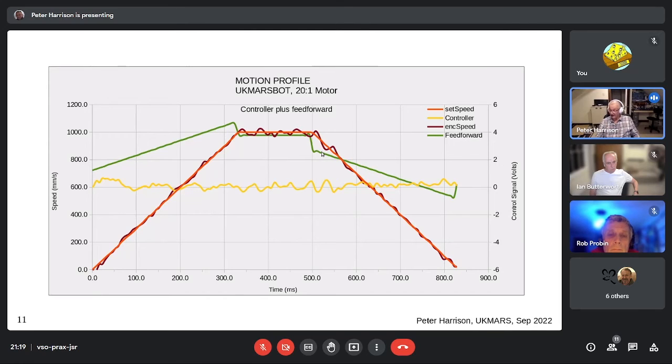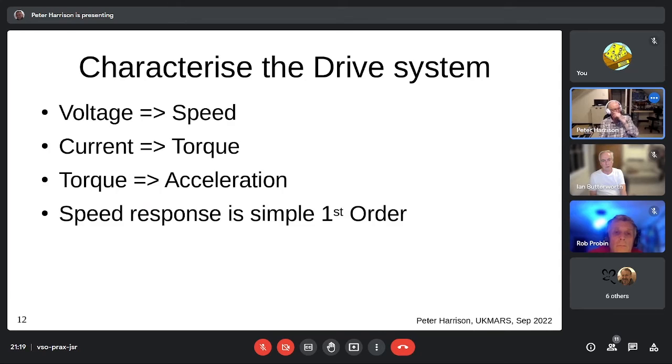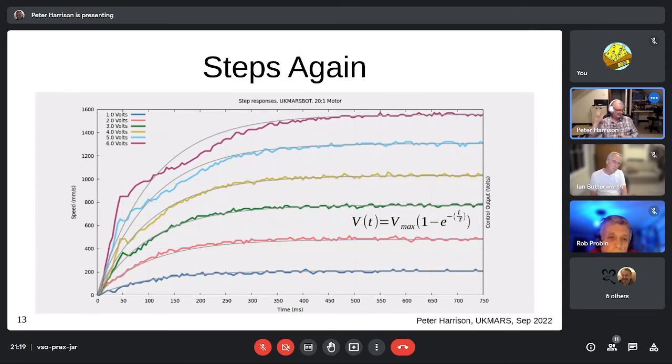And you might reasonably then ask, well, that's all very well, but how do you know how big that step should be? Well, it's actually easier than you might think. Look at this again, and consider what's going on at time 0. Down here, the motor's accelerating. And the faster we want it to go in the end, the harder it has to accelerate to get there. Yeah? So the slope of this curve at time 0 is the acceleration, right? Because acceleration is just the derivative of speed against time.